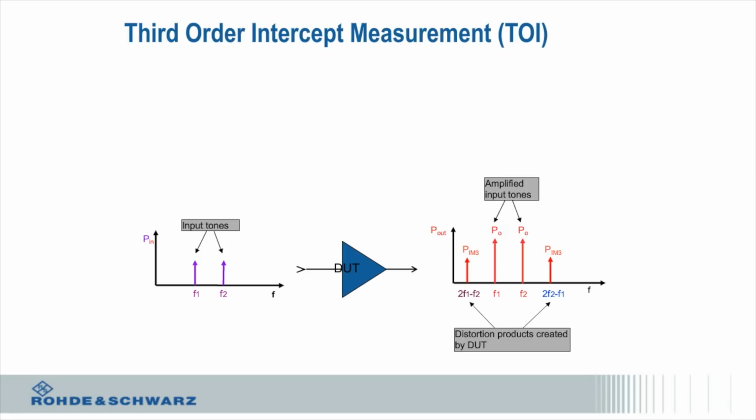So this is typically a trade-off. When you go back and look at the noise figure of an amplifier, things that typically have very low noise figure, or add very little broadband noise, typically have lower intercept points. So you have to use that cascade analysis to actually determine what amplifiers to put where. And this is really kind of the magic sauce of RF design.